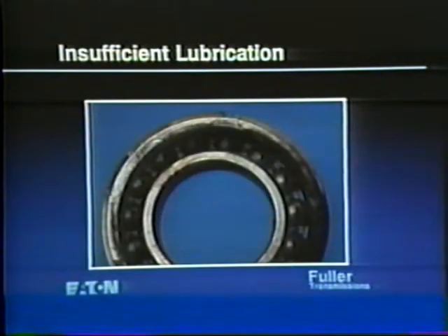As with gears, bearings can fail from insufficient lubrication. Failures from lack of lubrication are characterized by discoloration of the bearing parts, spalling of the raceway, and possible breakage of the retainers. Burning of the bearings and gear usually occurs together, so check out the bearings if burned gears are found. To prevent lubrication failures, follow the recommendations in the lubrication brochure Form 121.